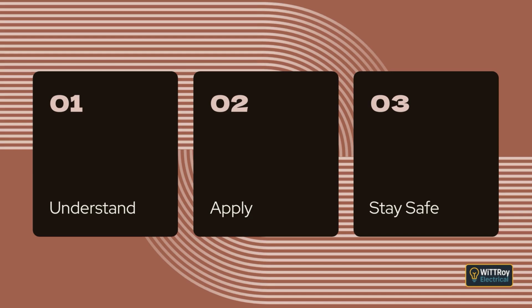Clause 2.6.3.3, Home medical patient treatment installations. Clause 2.6.3.3 applies to homes where medical electrical equipment is used under the rules of ASNZS 3003. These installations must be supplied by a dedicated circuit, be protected by a Type A RCD rated at 10 mA, and allow the patient or carer to reset the RCD if needed. The idea is to provide both safety and practicality in home healthcare environments.